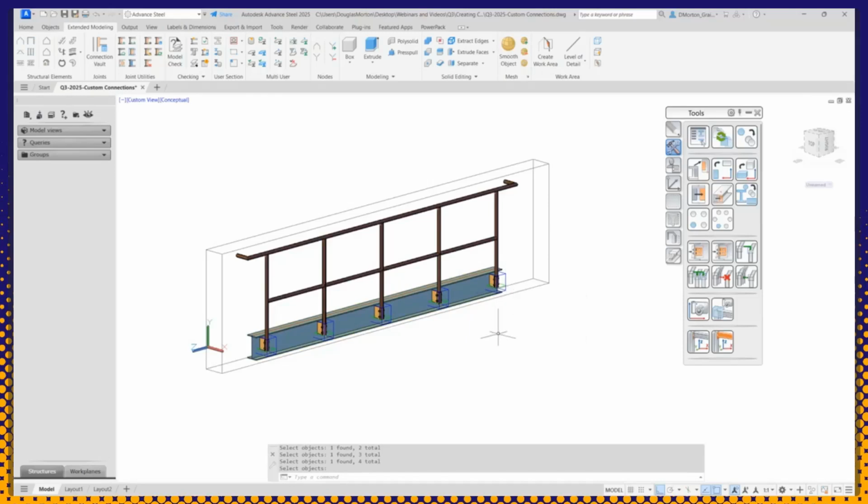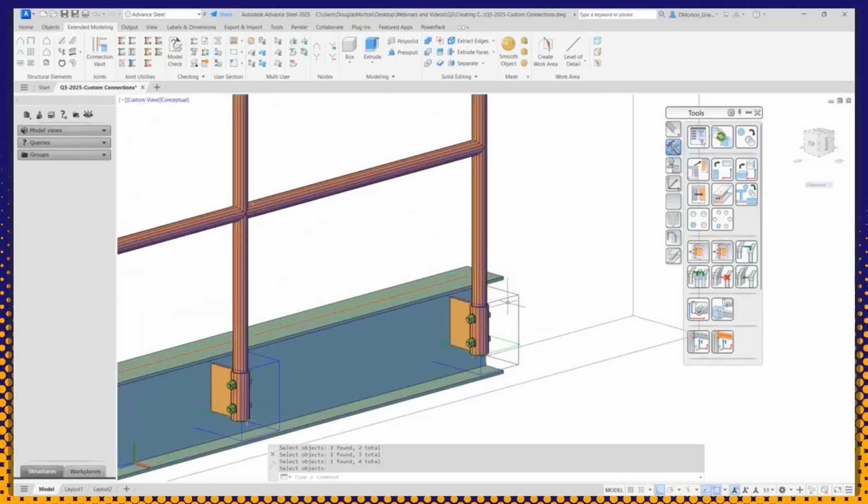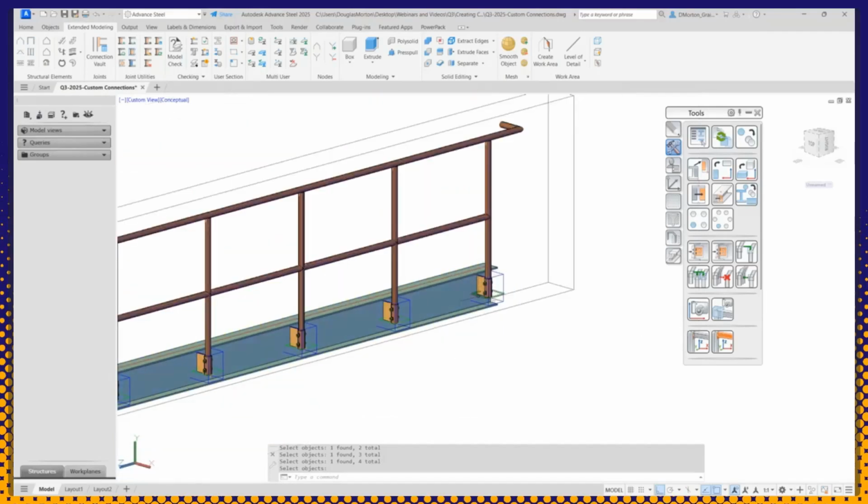Now, in some cases, depending on the handrail, you may notice that the final post is rotated. Okay, so if you do, just don't put the connection on there. You have two choices, right? You can go in and create a new connection, one for left and one for right. That'll work. Or you can do all of them as a joint connection and then just do this one separately.